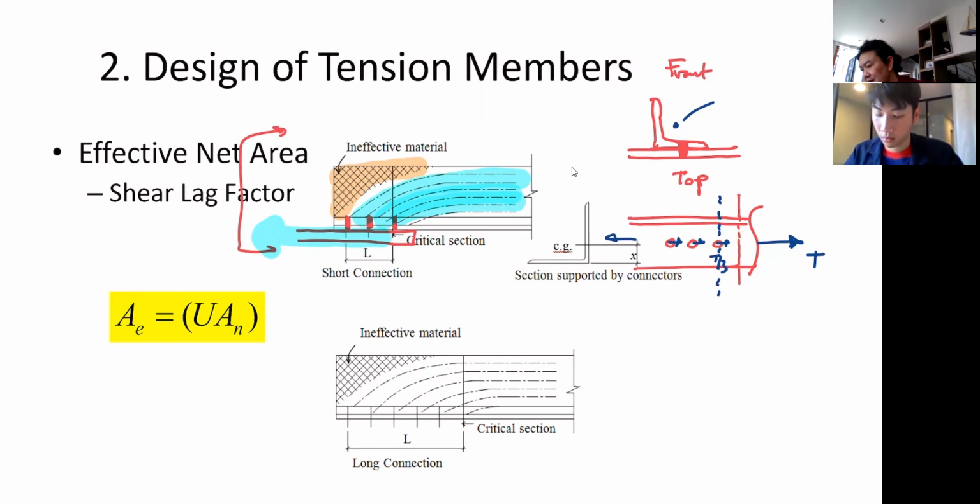But when you move to the second line, 1/3 of the force has already moved through the first bolt. So at the second line, you only have 2/3 of the force left in the member. This is a basic free body diagram. So that is why if the rupture is going to occur in the member, it will always occur in the first line of your bolts, correct?